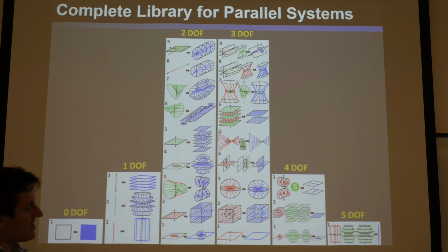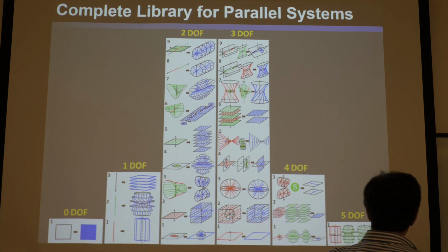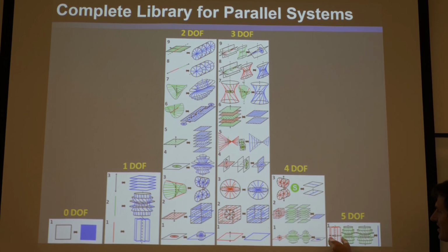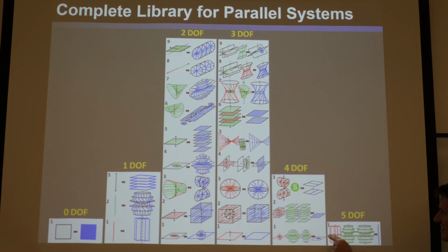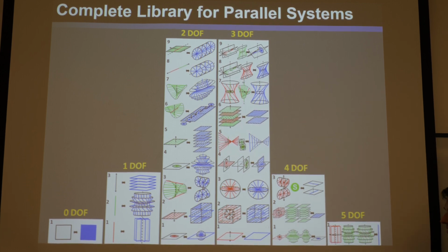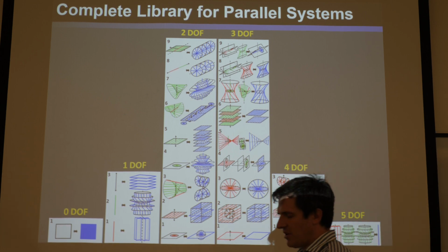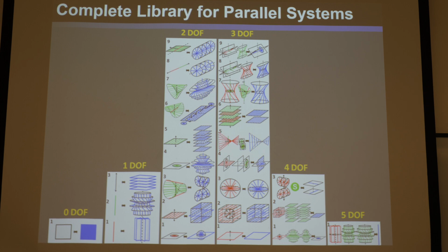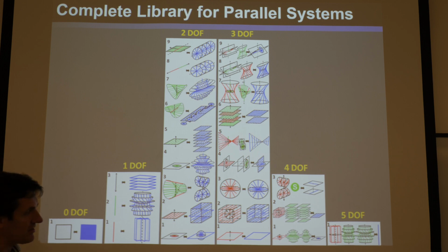And by the way, you'd see its freedom space right here. So here's the constraint space. It's a single wire, and its freedom space is here. It's oriented up and down. You can see the intersecting red planes, and here's the disk of translation arrows. There is a ton of screws in there as well. The green screws. We'll talk about those. You'll recall those are twists with a finite pitch, but I haven't shown you how to find those. So there's a bunch in there. So that's the freedom space.